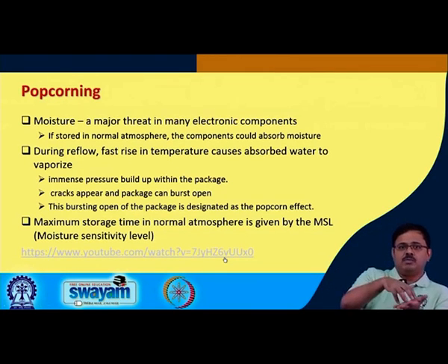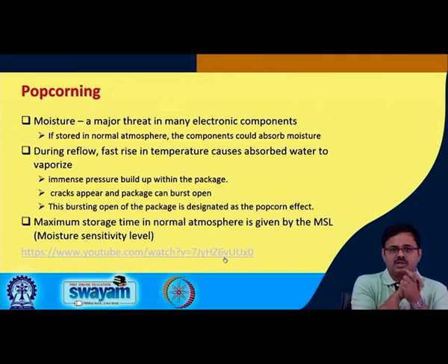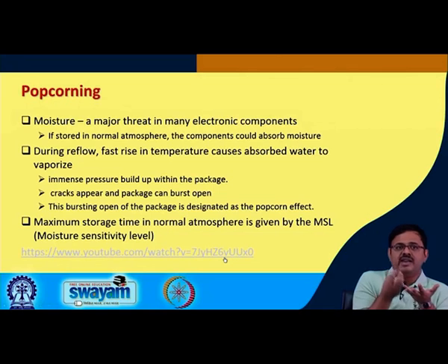Now, let us say I put this component on the circuit board and I do the reflow process. What will happen? Because of this fast rise in temperature, the absorbed moisture will vaporize. When water vaporizes, its density decreases, so it will create immense pressure.